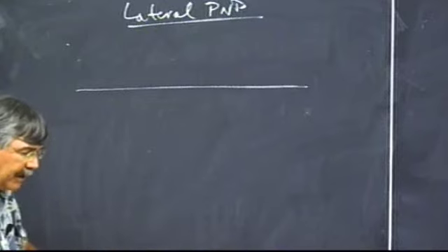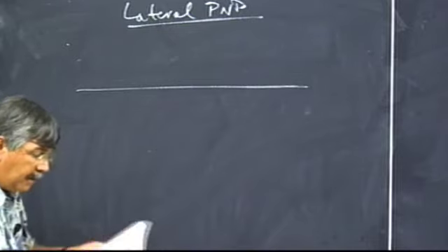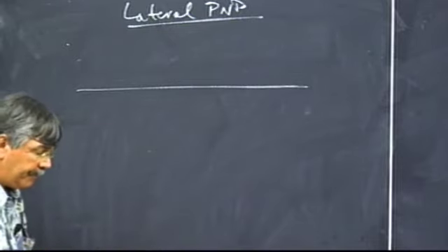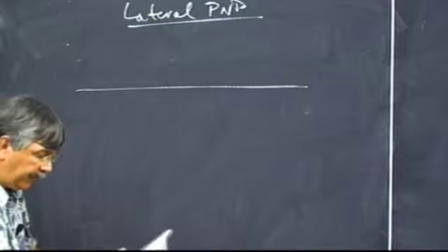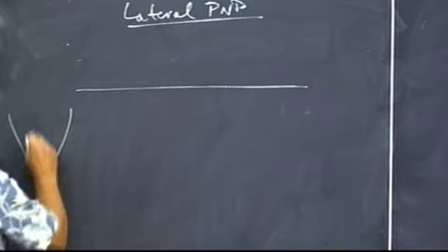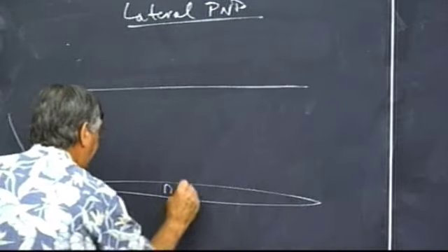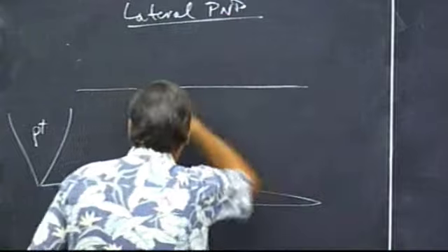So I'm looking now at page 7, 8. I don't have a picture of one. Yeah, I do. All right, the best picture is on page 7 of the handout. So basically what we're going to do is take maybe this junction isolated thing with the P plus, with the buried layer down here, the N plus, the P, and here's the surface.